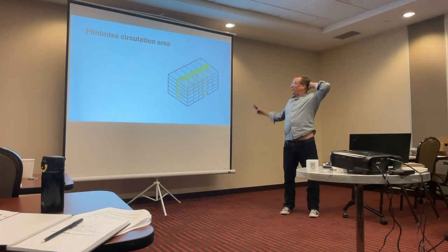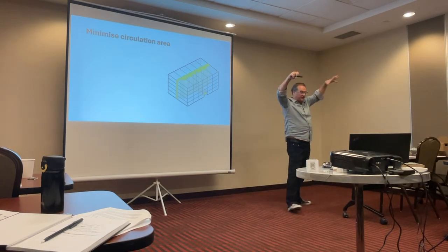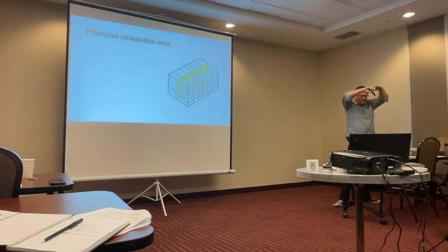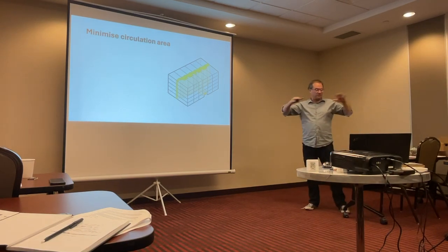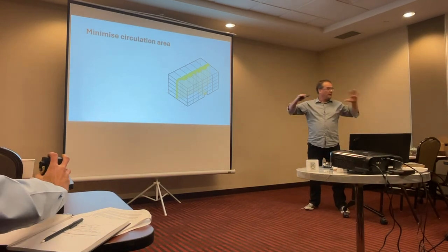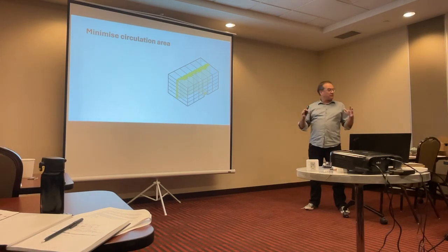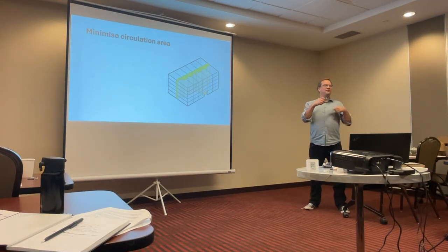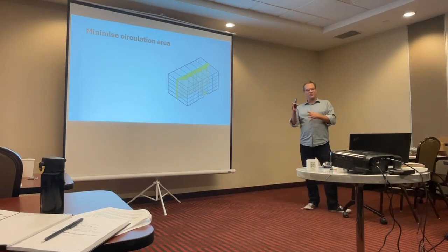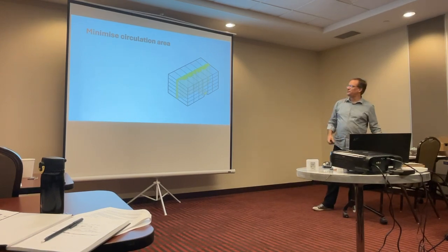Okay, so then for the architect, once you've created a building that is still beautiful and wonderful and serves all your other purposes, because we're not saying take away architectural values at all, but with the best form factor that's reasonably possible, then let's look at circulation area. And we'll probably revisit briefly, the Passivhaus Institute counts the circulation area at 60%, not 100%, and that is in part to promote this thinking, and it's also traditional cultures in Germany.